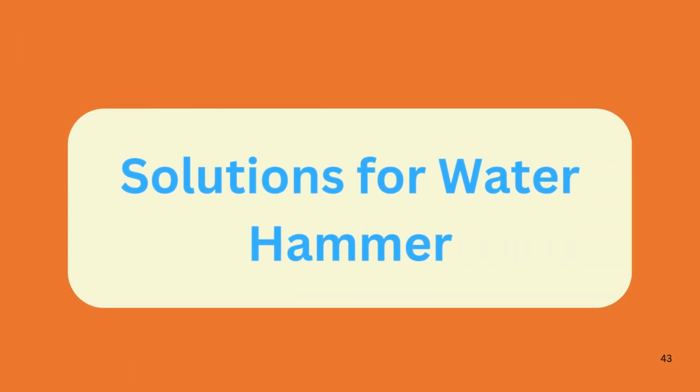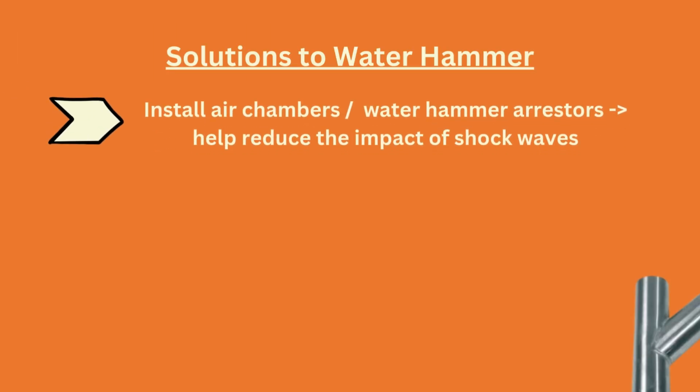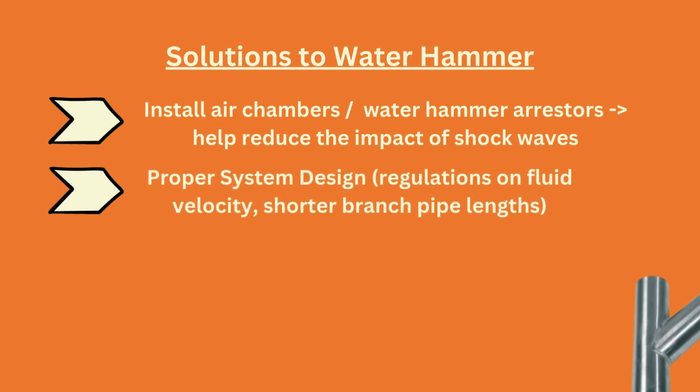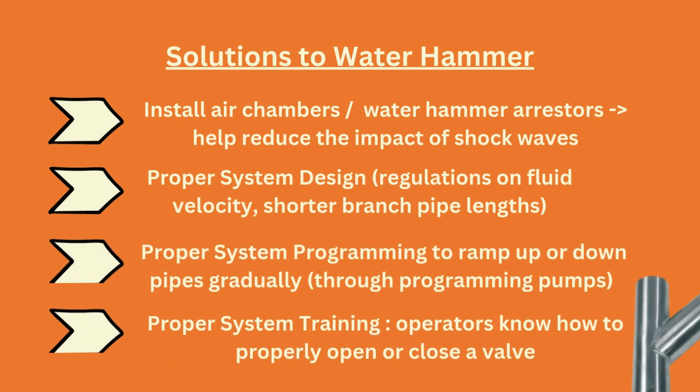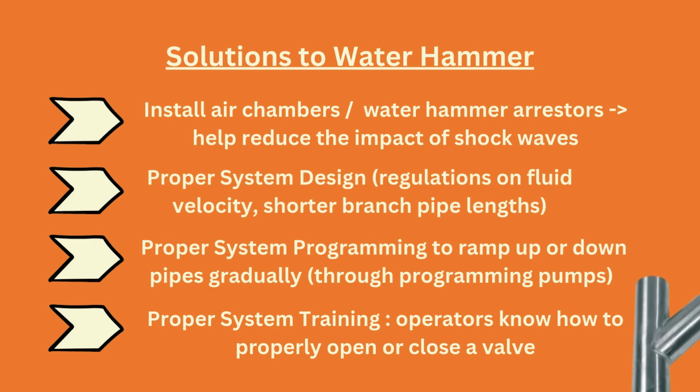Now let us talk about the solutions to the water hammer, one of which will be to install air chambers or water hammer arresters to help reduce the impact of shock waves. Next will be to have proper system design and programming where pipe modifications have to be made. Next will be to have proper system training where operators are taught how to properly open or close a valve. That being said, that sums up our video on the water hammer. Thank you for your attention.